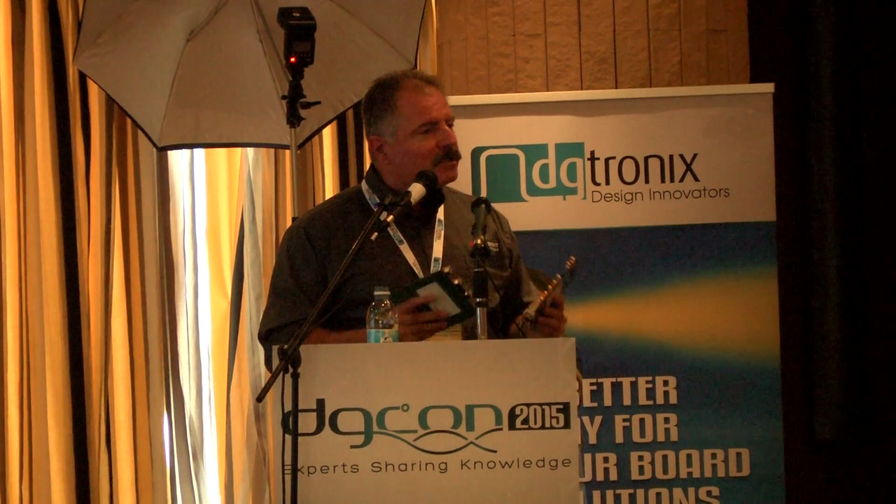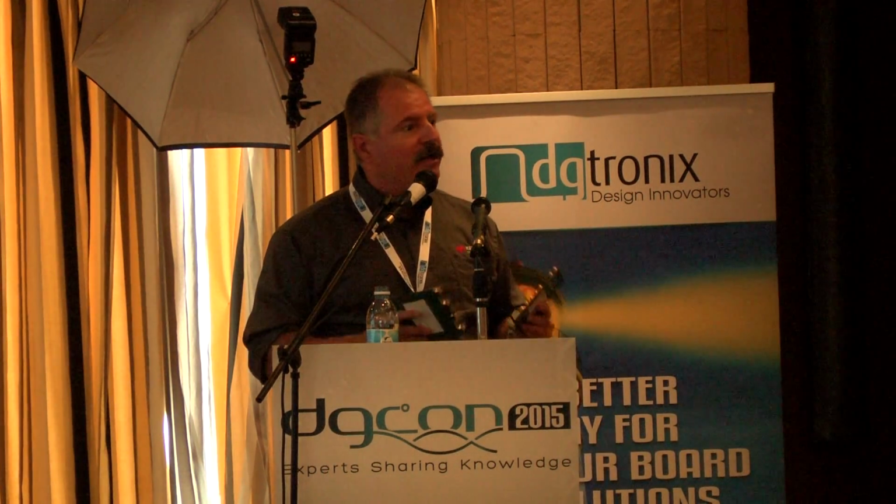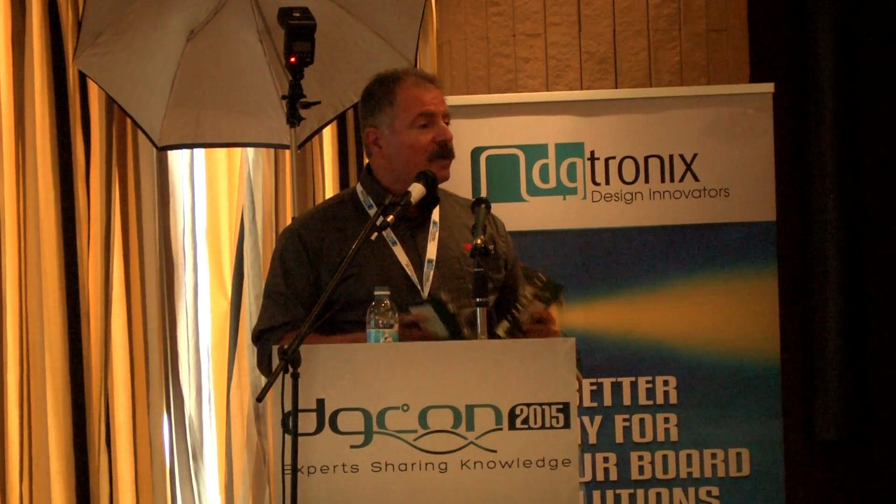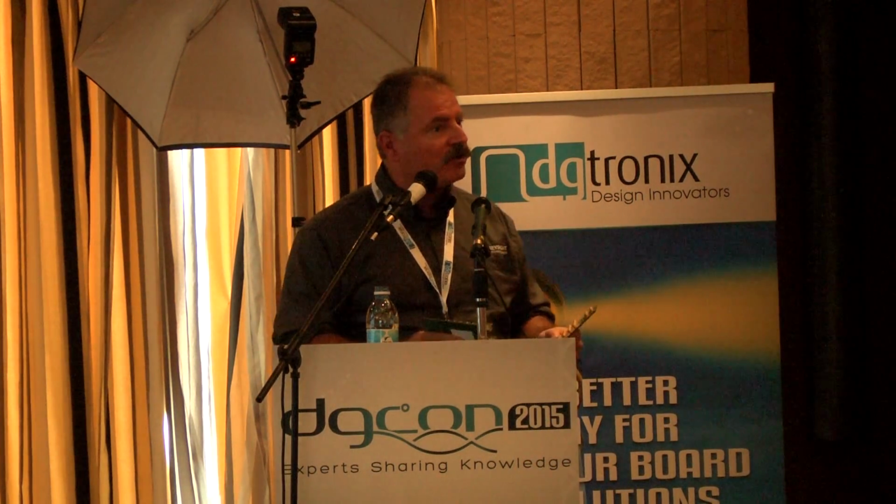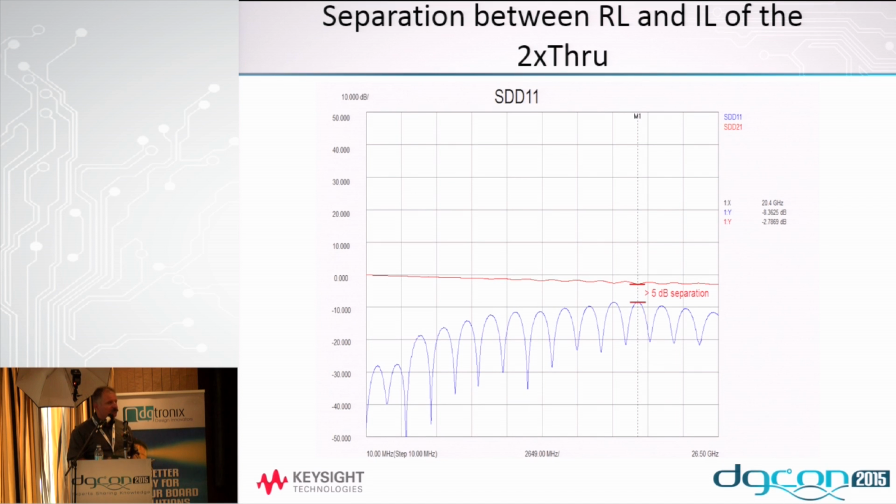Wrong. You need to spend as much time with the test fixture design as you do the actual device under test. You can't take a poorly designed test fixture, de-embed it, and expect to get high frequency performance measurements. Okay? So this may not be intuitive at first, but once you realize it, you can do a design that works well. So the rule of thumb here is spend as much time designing the fixtures as you do the device under test. And it'll help you down the road when you're doing de-embedding and other types of error correction also.